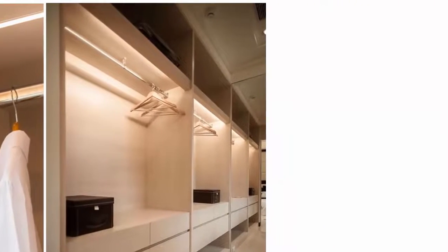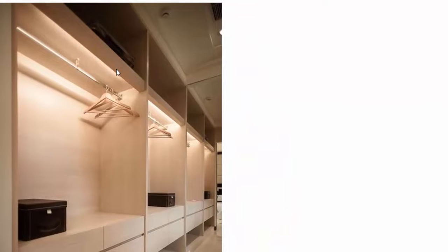What I can do is place a strip light or linear LED light in front of this clothes rail so that the light illuminates all the clothes. The second option is concealed lighting, wherein we need to have a provision within the closet so that we can hide the fixture at the top portion of the closet and direct it towards this side. In this way, the light fixture is not visible, but you can see that your whole space is bright and nicely illuminated. I love this idea because it is a very neat solution.